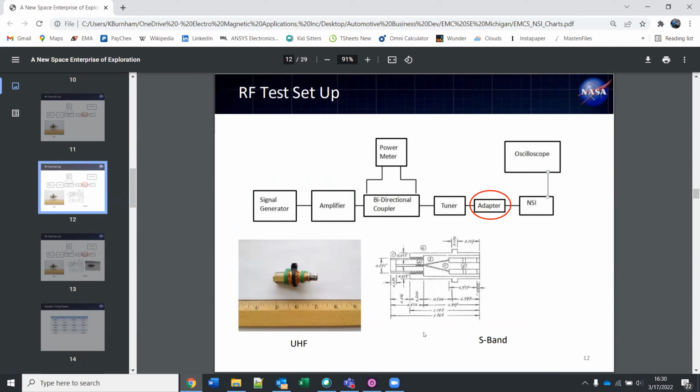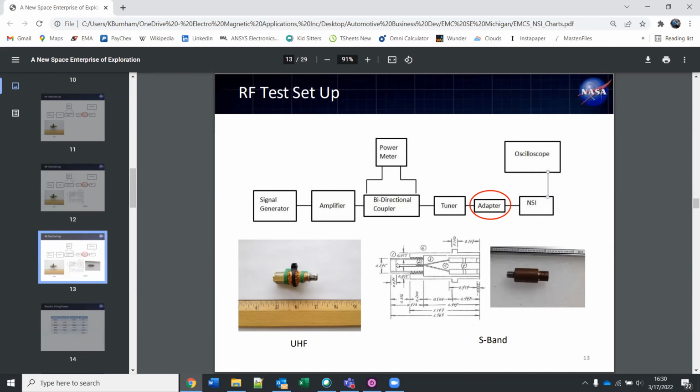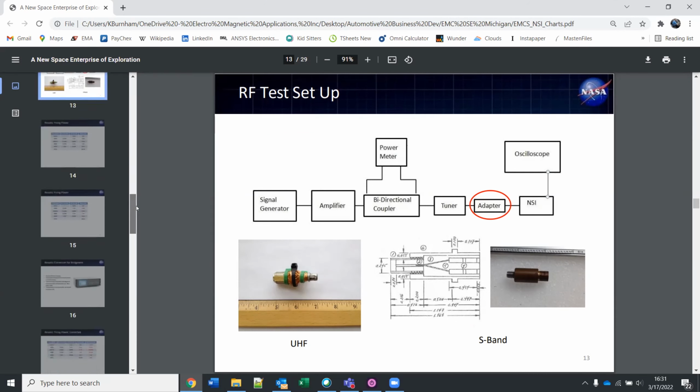So this is the drawing that I came up with of a custom made adapter. So not so much taking two existing things and then using some foil and zip ties. We actually ended up having this machined. Basically, what I tried to do was take an SMA connector, the shortest possible one I could find, take that center pin, match the dielectric of the coax with the dielectric inside the adapter, and taper the connection instead of trying to go straight out and then T-barring across it, basically trying to make the geometry of it as gentle a transition as possible. And I'll be darned, it did end up working.